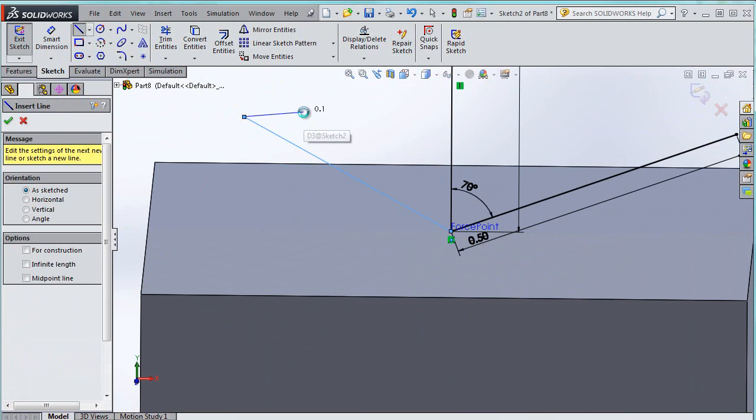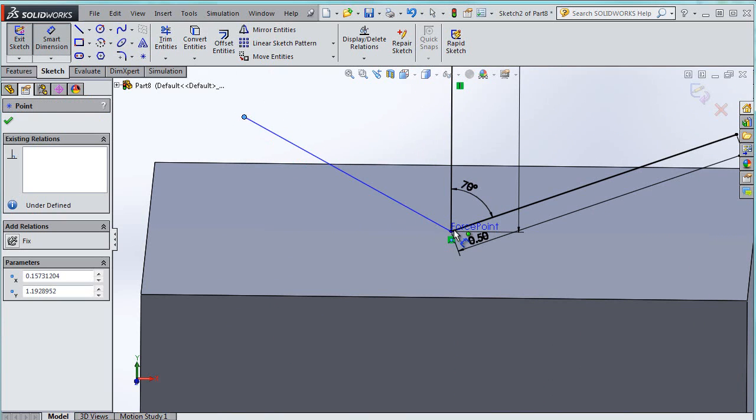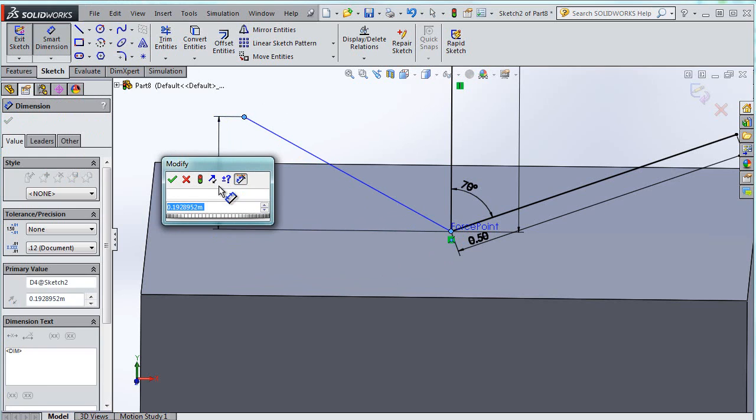Now, this one doesn't have an angle. Instead it has a 7 and 24.25. The way that I can achieve that is I can go point, point, and now if I go like this, I can do that dimension. This is this way, so I know that this one is the 7. Now I don't want it to be huge, so I'm just going to say 0.7.